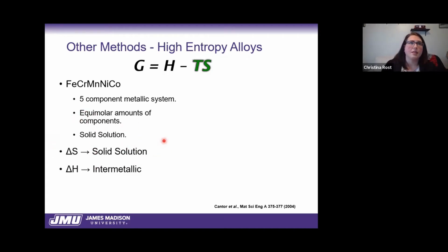So the idea is if S is the dominating term in minimizing the free energy, we form this solid solution. That's great. But if delta H is the dominating term in minimizing the free energy, we end up with some intermetallic. And these systems certainly exhibit very high entropy, and they have certainly interesting properties. But there's been no real proof of entropic stabilization.